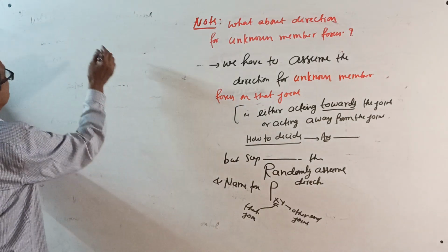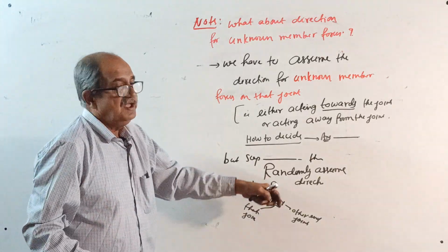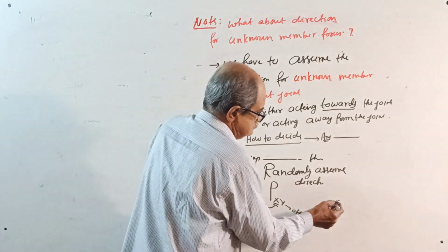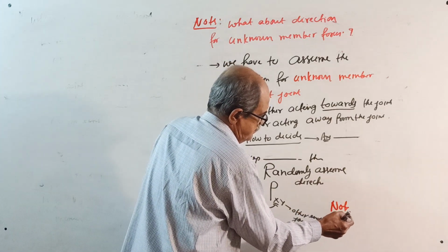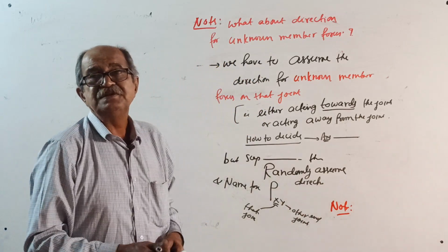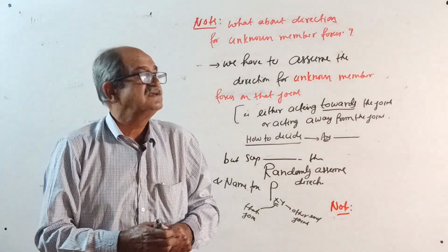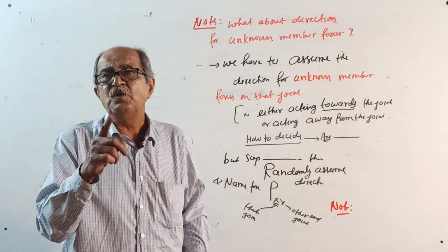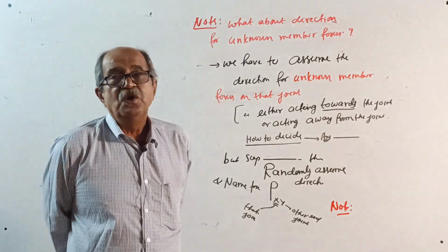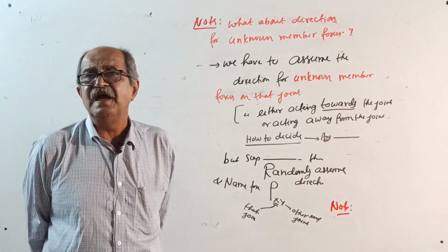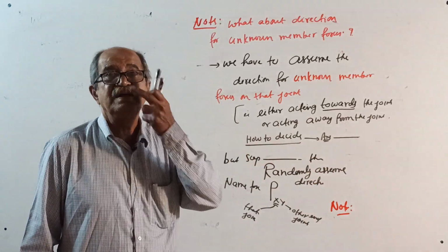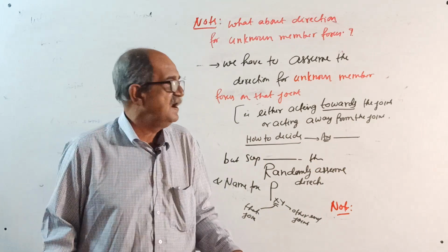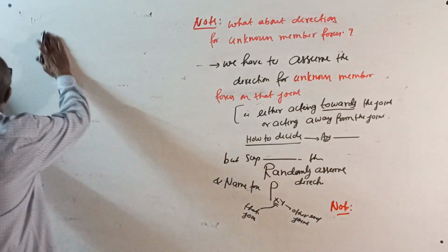Okay, this is also over. One, make a note here. One very powerful note you have to make now. Note: after the joint is completely analyzed or unknowns are calculated, always calculate unknowns with sign. Positive sign indicates that the assumed direction is correct. Negative sign indicates that the assumed direction is wrong. Write that way.